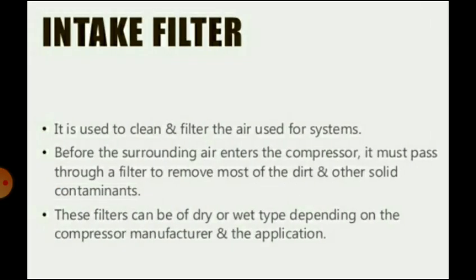Then we will see the components of the pneumatic system one by one. First is the intake filter. It is used to clean and filter the air used for the system. Before the surrounding air enters the compressor, it must pass through the filter to remove most of the dirt and other solid contaminants. This is the first stage before the air reaches the compressor. These filters can be of dry or wet type depending on the compressor manufacturer and the application.